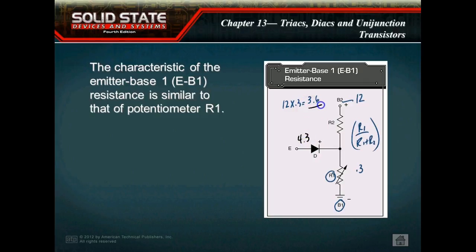So this is a PN junction. What do we have to turn this thing on? Over here I would have 3.6 volts, so I would have to make this 0.7 of a volt more positive. Do y'all understand that? And then this guy here would turn on. When it turns on, this guy here drops down to pretty close to 0 ohms.